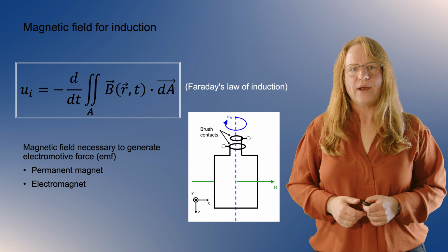And then if we go to the next outer loop and integrate once along the complete loop, the electric flux is also the same I, and the same is also true for the third loop. So we learn from this that as we are further away from the conductor, the contour integral is a longer path, and because the path is getting longer, the H field is getting lower. So the H field is dropping as we increase the distance from this conductor.